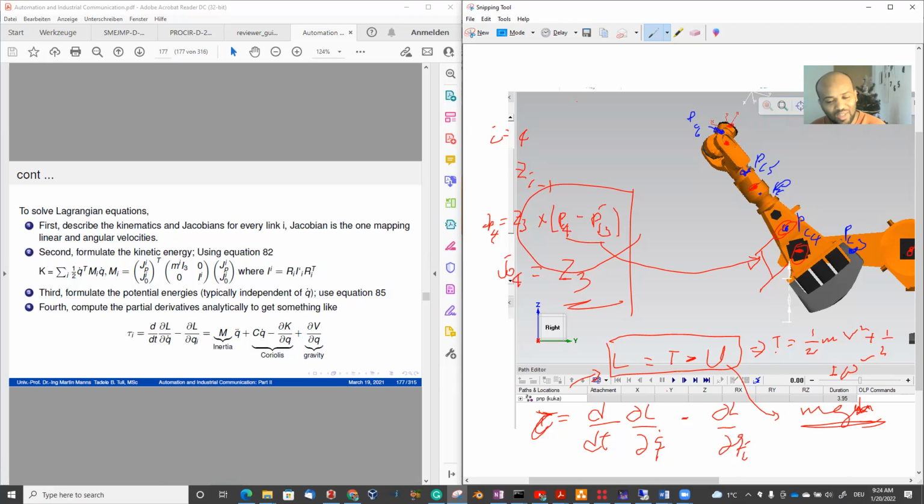In kinematics, we know the homogeneous transformation matrix, composed of 4x4 matrices derived based on the Denavit-Hartenberg convention. The Denavit-Hartenberg convention is a convention to represent your homogeneous transformation matrix in a systematic way by describing your joint variables. A joint variable means theta, which changes in your robot mechanism, which we call the actuation angle, or just joint variable.